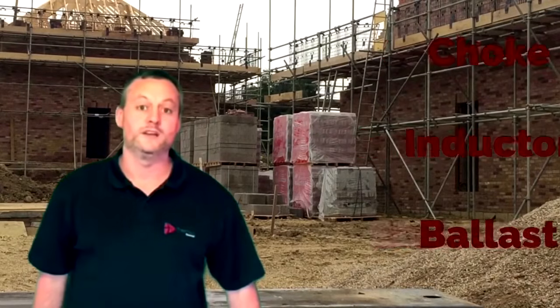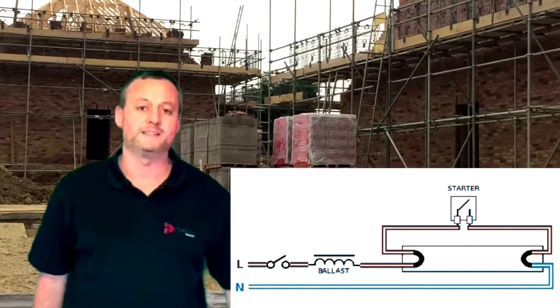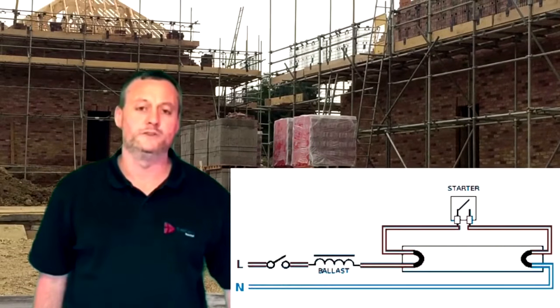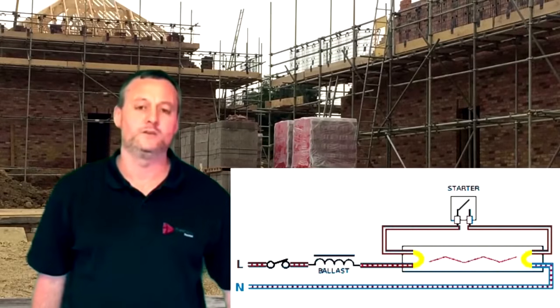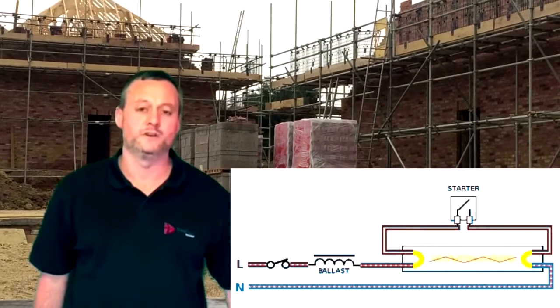When the fluorescent lighting circuit is completed by closing the switch at the door, the circuit is made through the ballast itself. Remember, it can be called a choke or inductor. Circuit then goes through to the starter. The starter blades are in the open position. The heat is generated in the neon gas in the starter, causing the blades within there to close. Circuit is completed round to the other side of the tube.